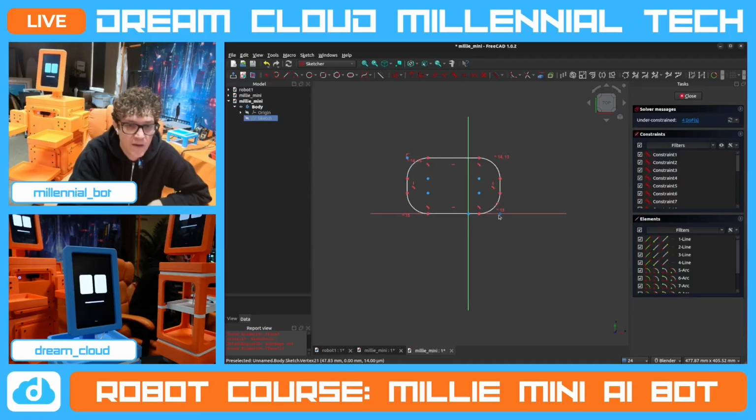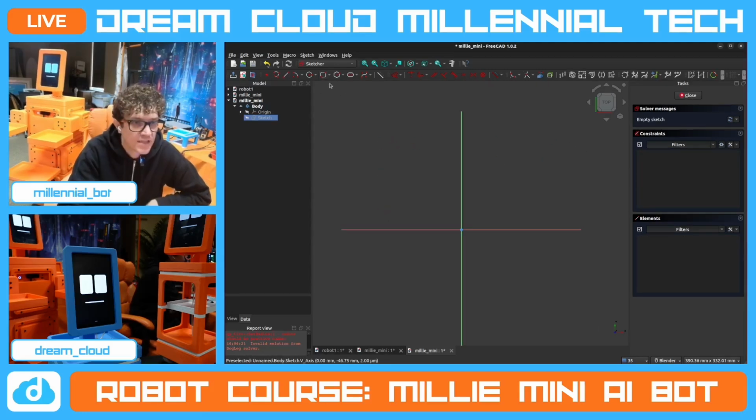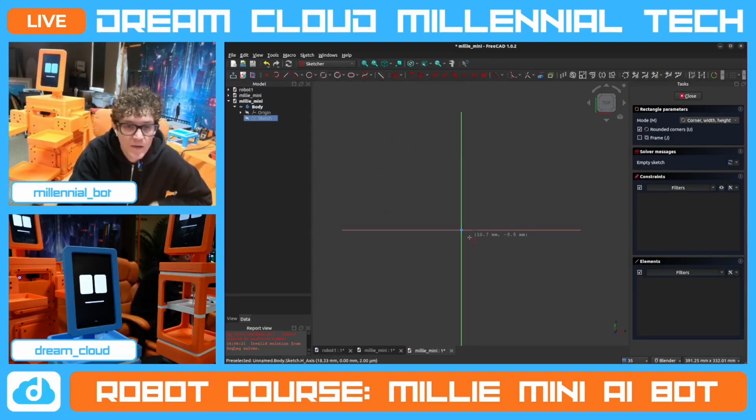And because that was kind of born on there, then it actually is kind of conditional to that point. So it's only really just kind of sticking to this one axis, and then it's got all these other degrees of freedom. Essentially, we want to do the same thing, but instead of starting it on the corner, which is how this works, we want to go over here and select the center, width, and height. So this one is the corner, width, and height. That's the default. I like to go with the center, width, and height, and I'll show you why.